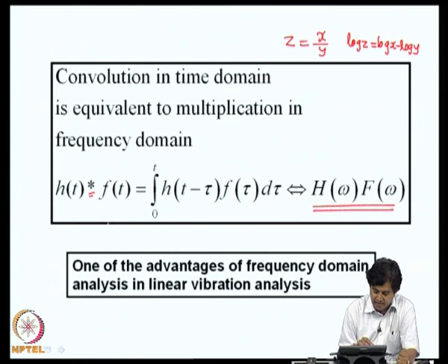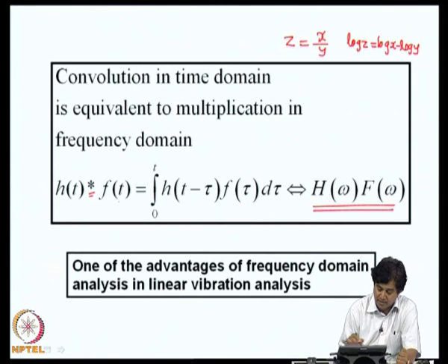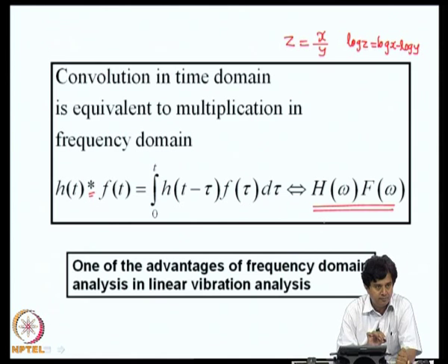This will be effective if and only if the movement from time to frequency and frequency to time is easy. Just as you have a log table and an anti-log table, you should be equipped with either a table of integrals or efficient algorithms for moving from the time domain to the frequency domain and back. The fact is that there are very efficient algorithms, known as fast Fourier transform algorithms, which enable you to move from time to frequency and frequency to time.